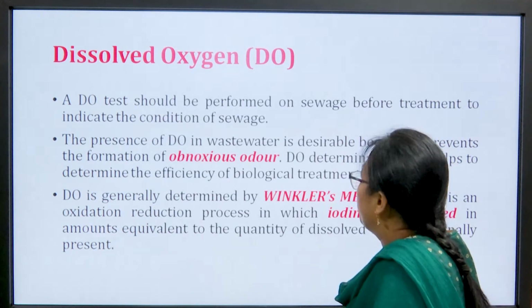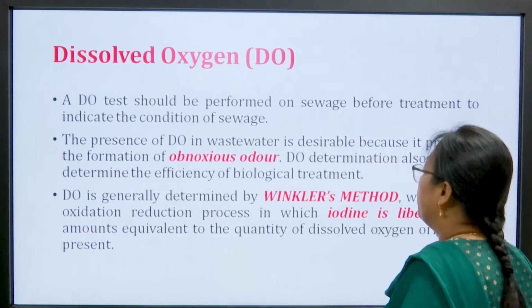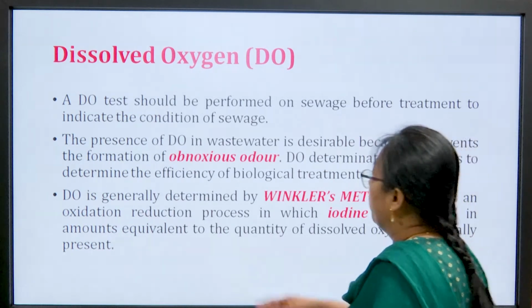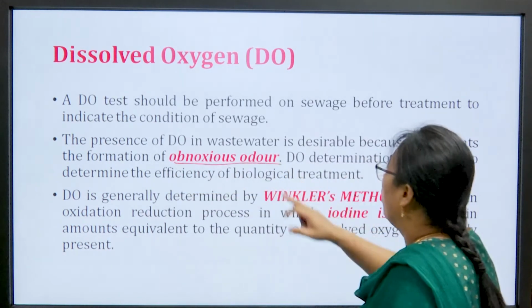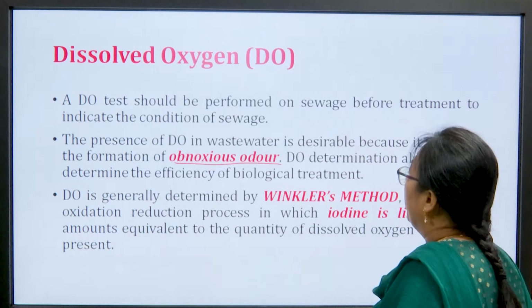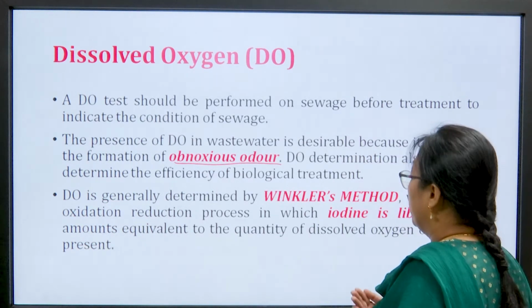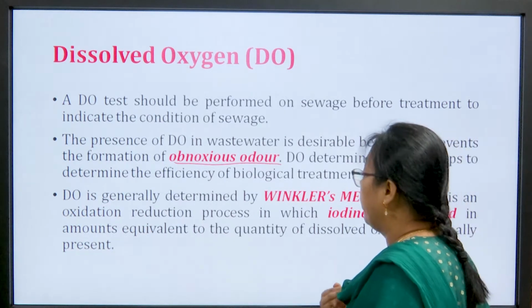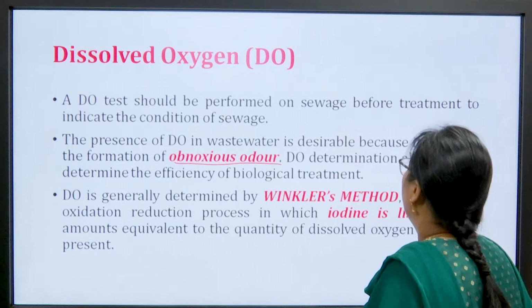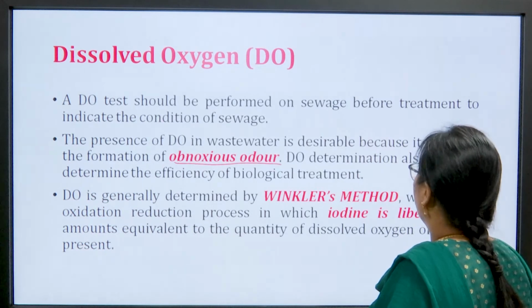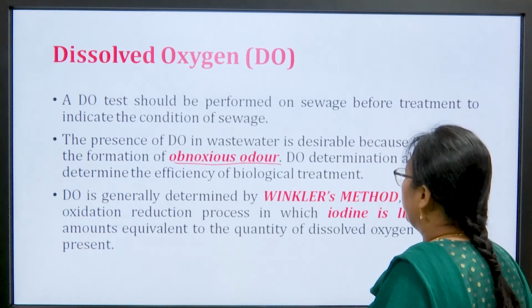Presence of DO in wastewater is desirable because it prevents formation of obnoxious smell. If oxygen is not there, then what will happen? It will start giving a very bad smell because of the hydrogen sulfide presence and all. Okay. DO determination should also help to determine the efficiency of biological treatment.